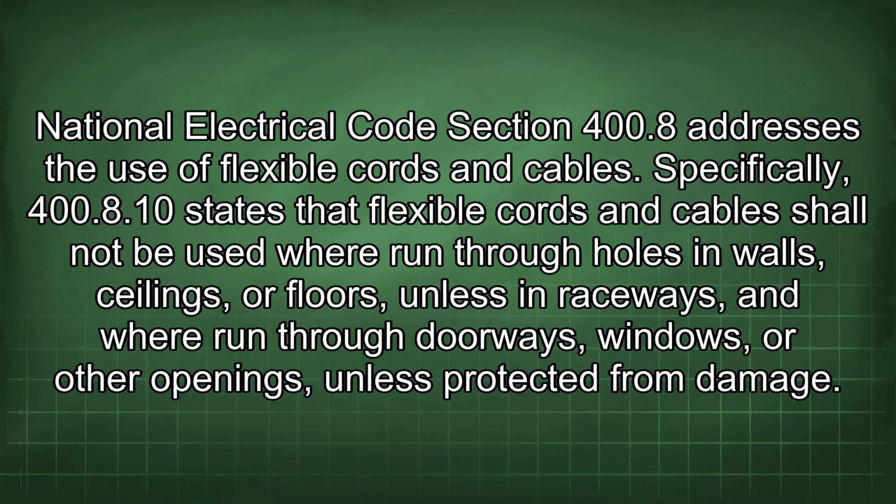National Electrical Code Section 400.8 addresses the use of flexible cords and cables. Specifically, 400.8.10 states that flexible cords and cables shall not be used where run through holes in walls, ceilings, or floors unless in raceways, and where run through doorways, windows, or other openings unless protected from damage.